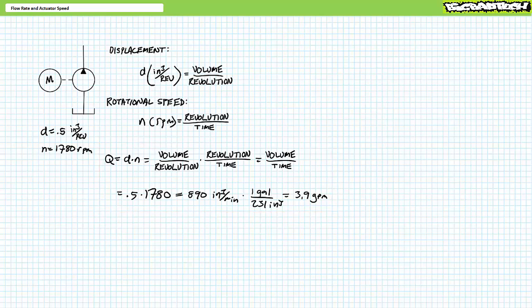Again, flow rate calculations shouldn't be that hard. Any difficulty you have with this topic may be because of unit conversions. Stay neat, stay organized. You note two properties influence the flow rate output of pumps, namely displacement per revolution and revolutions per minute. This implies pumps can vary their flow rate output by varying one or both of these properties.